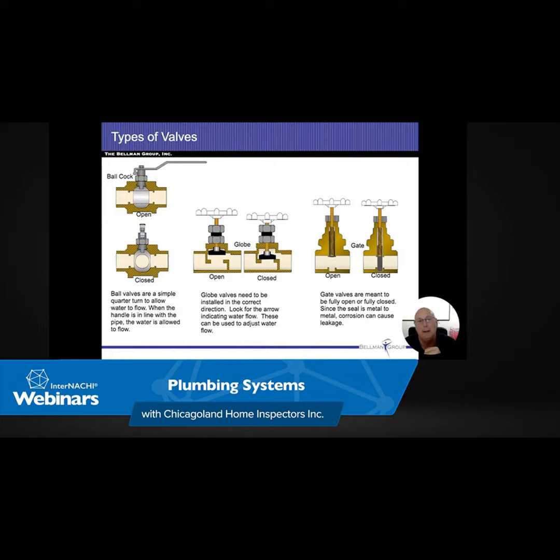So we just keep pumping water into the tower. They could turn more pumps on as needed and turn pumps off as needed, depending on the height of the water inside of the water tower. So they try to maintain a steady static pressure. The reason why they want that to be steady, no matter how much water is being used, obviously we use more in the morning as a community than we use during the middle of the day, or if there's lawn sprinkling going on versus nighttime. The reason why they want a steady pressure is when you change the pressures of the water pipes in the ground, that actually shocks those pipes. And if they change significantly, they break the pipes, and they break them often.